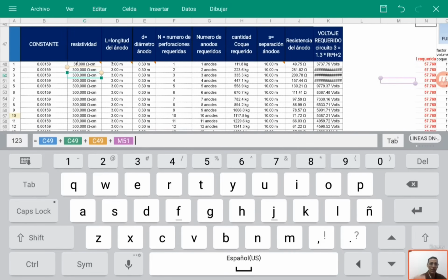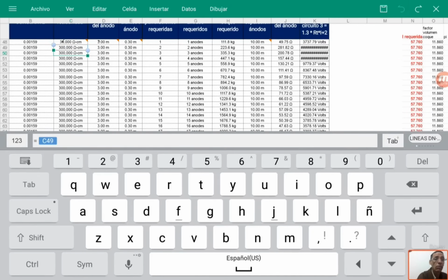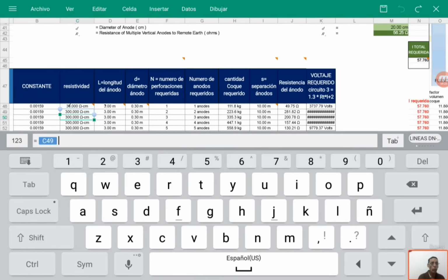Every decision, every value, every concept we assume, exposed area of material, current density, whether it's due to the environment or the quality of the coating, soil resistivity, the length of the anode, the number of anodes. If I increase the number of anodes, the resistance goes down, and if the resistance goes down, obviously that's going to benefit my circuits. So, clearly, all these considerations affect our design.